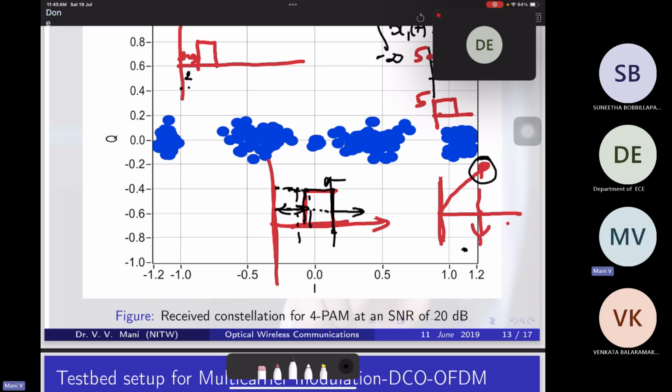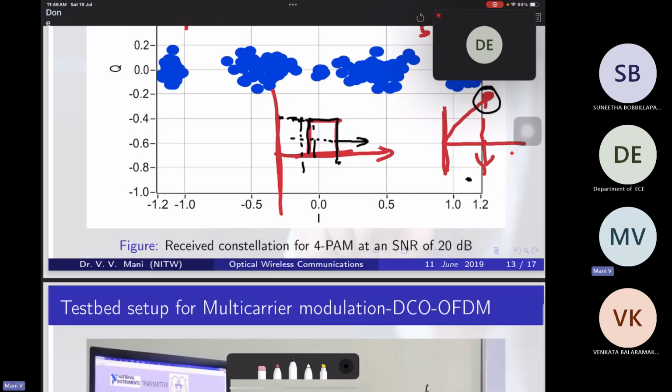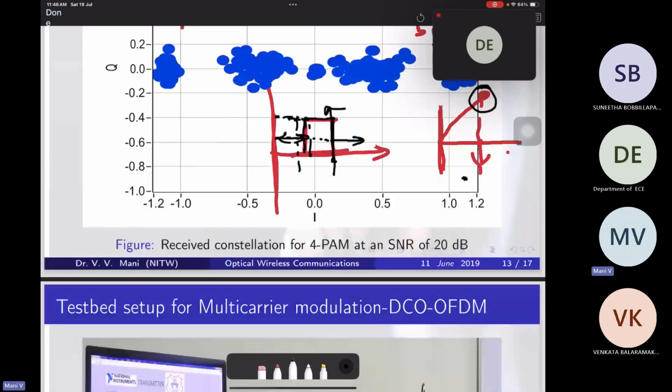We do a lot of math to establish this concept. So we do the delay estimation, and we fix that estimation when receiving the signal. Suppose that estimation is 1 millisecond or 1 microsecond, I'll fix my window after 1 microsecond only, and track my output signal. Okay? This is a very useful area of research in communication. Synchronization is one of the most critical issues in communication systems.